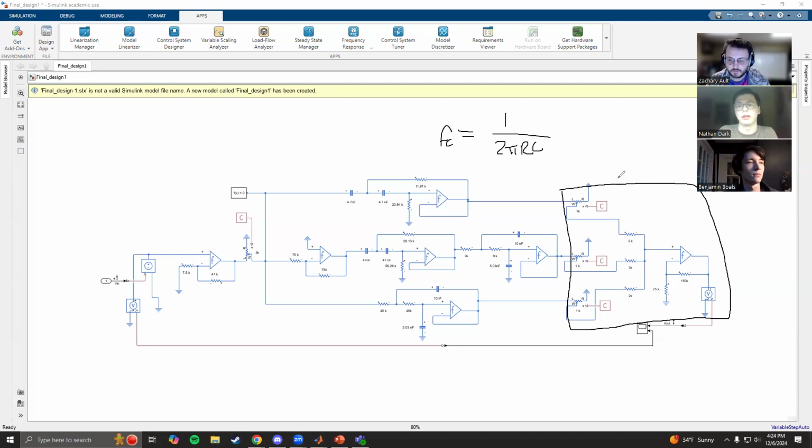So then they go into the adder circuit on the very right, and it just simply has a gain of 1. It just combines them. And then where the voltage source is located is where in our design our speaker would be. We just couldn't put it in the simulation. So the adder circuit simply adds them together to then be driven into that speaker.